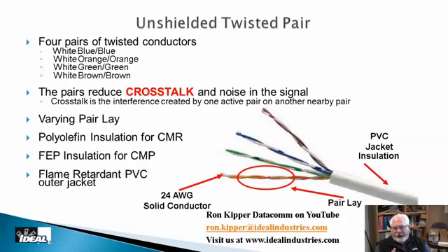Now, when you look at all those cables, they will have 4 pairs as a general rule, and those 4 pairs are color coded. They're blue, orange, green, and brown. Line 1 is supposed to be blue, line 2 is supposed to be orange, line 3 is supposed to be green, and line 4 is brown. If you want to know more about wire color code configurations, I certainly have a couple videos up on the channel, especially as we talk about terminating category wires. The colors are part of the standard. So, do you have to make line 1 blue? The answer is no. More than likely, any color would work, but somebody coming in behind you would expect line 1 to be blue.